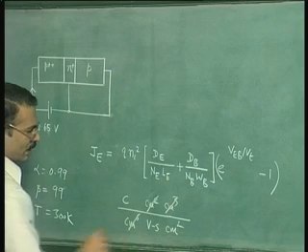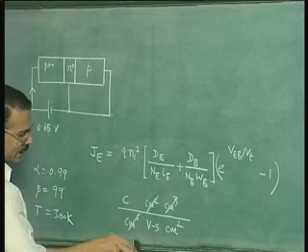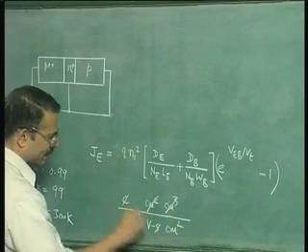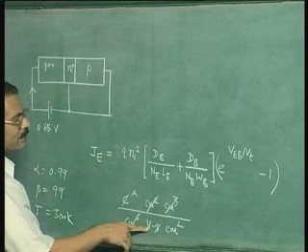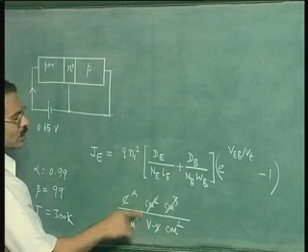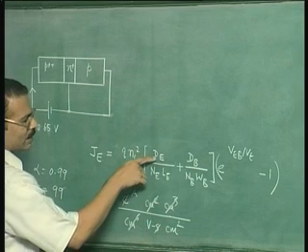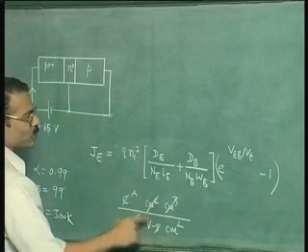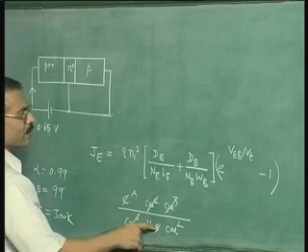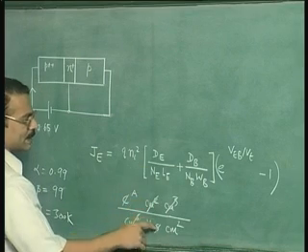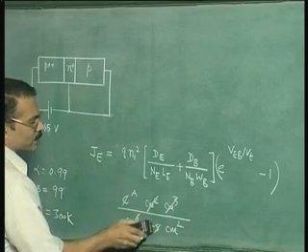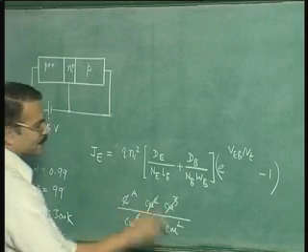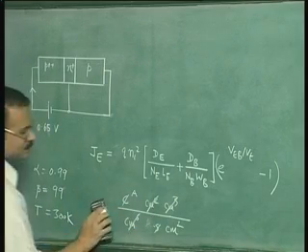Incidentally, we made a mistake here. We can see that because Coulomb per second is amperes, and you are getting this additional volt. This volt should not be there. So this was a mistake. The mistake was that the diffusion coefficient we wrote as centimeter square per volt second. This is wrong. Diffusion coefficient is centimeter square per second. Mobility is centimeter square per volt second. So anyway, we remove this volt and we find that it is ampere per centimeter square. This is the current density.